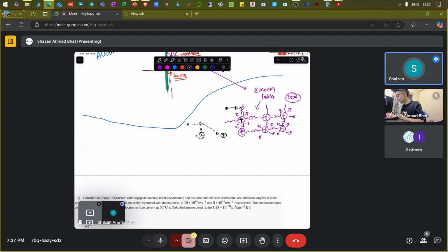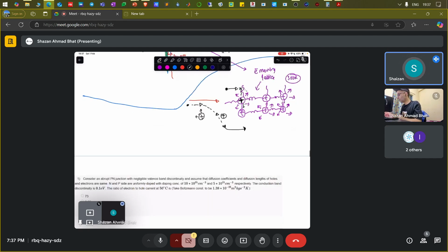And if another atom is vibrating, the electron moves in another direction. So instead of going through a straight path, the electron moves in a curvy fashion. That impedes its motion and creates resistance. These are called scattering events. They can be created either by impurities or by phonons. Phonons are these lattice vibrations.